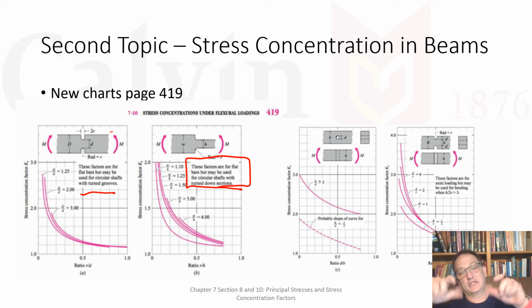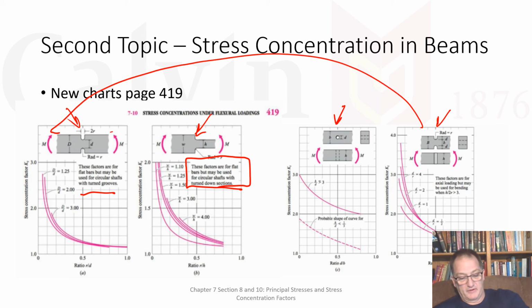That stress concentration is going to look the same whether this is a flat bar or a circular cross section. So I've got stress concentration factors for notches, for step down, for holes, and that looks like that's for grooves too. Oh, that's a notched bar. It's interesting that that's different than this, and maybe when you dig into the details it's not that much different.